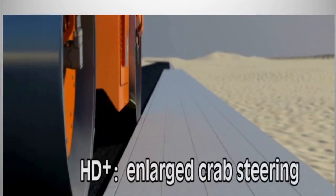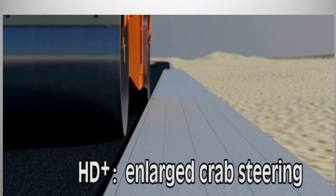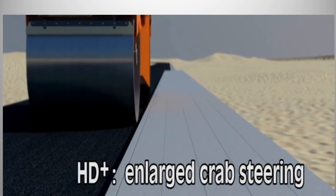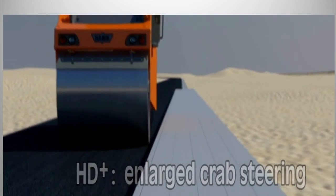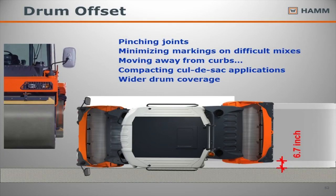You're going to actually put the front drum up against the curb and the rear drum is going to be away from it. Now the only way this works is you have to come off the curb. Don't stay on the curb, otherwise you're not going to be able to do that. But once you come off, the rear is away, so it's not going to tear out that new curb that you're looking at.